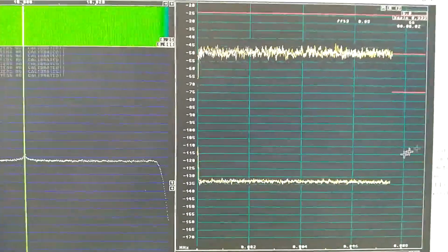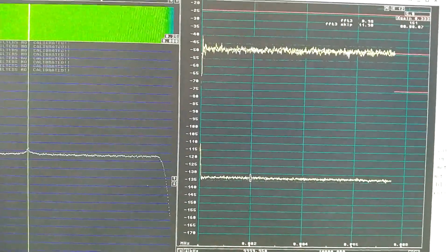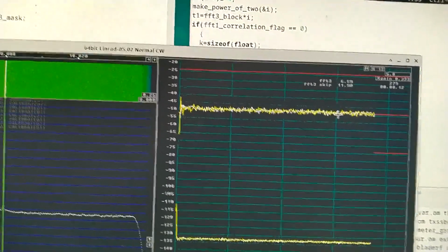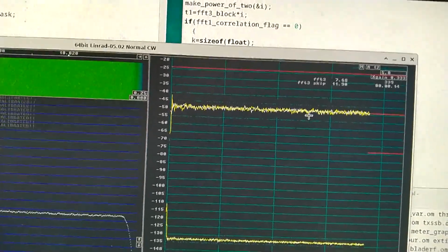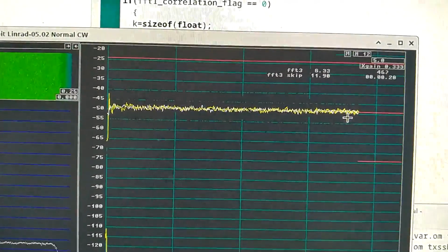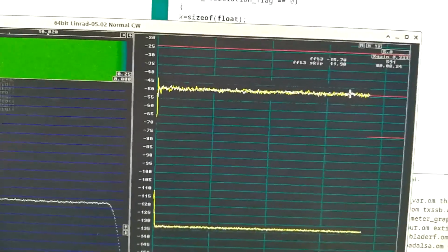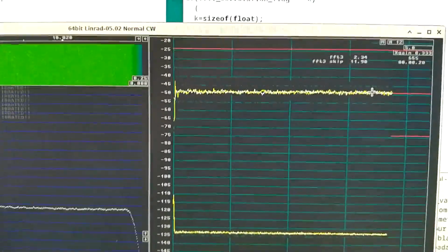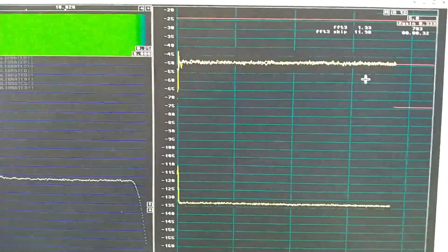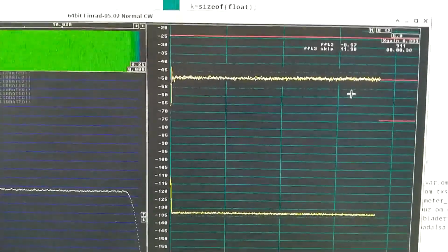And here is the modulation. The sideband noise is at minus 134. The correlation between AM noise and phase noise is 0, fairly accurately. And I have seen this in 20 seconds only, because the noise is high above the internal noise of the system. This is just to verify that things are doing what they are intended to do.